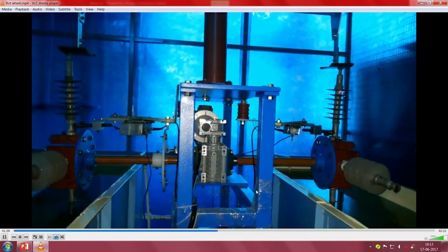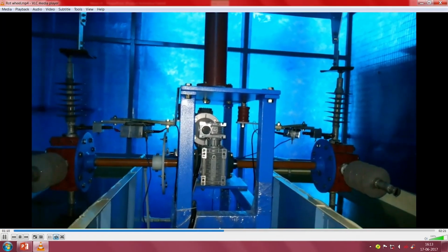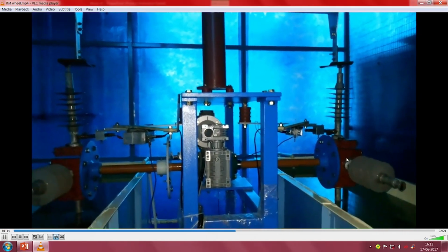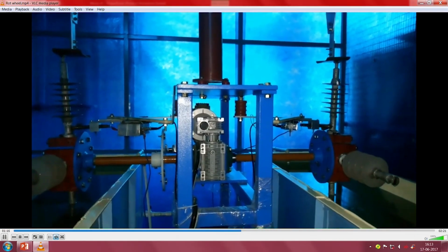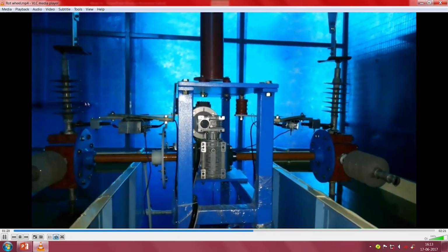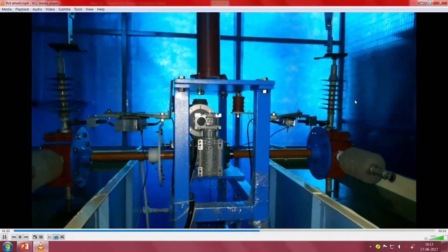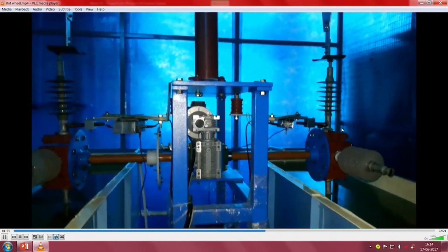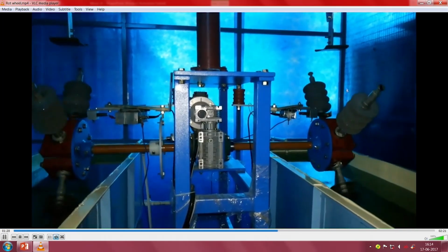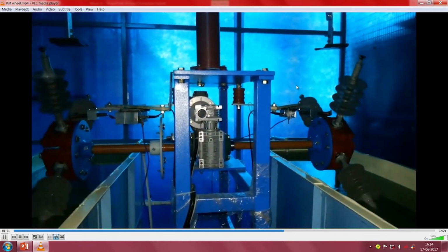with the protection, employing a digital storage oscilloscope and also a National Instruments module where you can capture the data for the entire 40 seconds period during the contact of high voltage. So, you can see the discharges, and after 40 seconds the insulator next in the line comes in contact with the high voltage. This transition is 8 seconds.